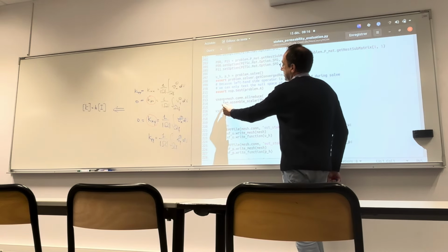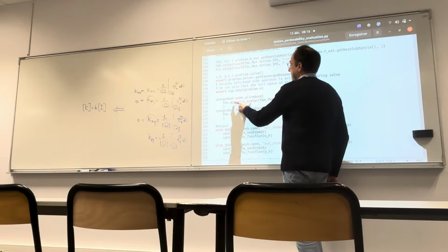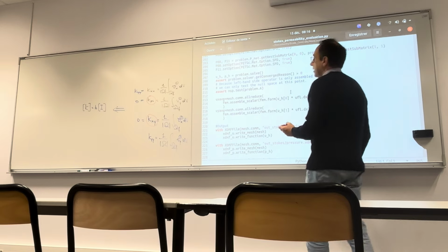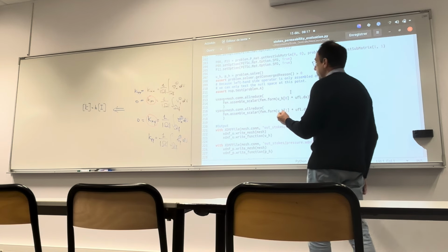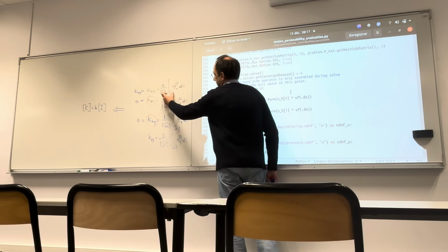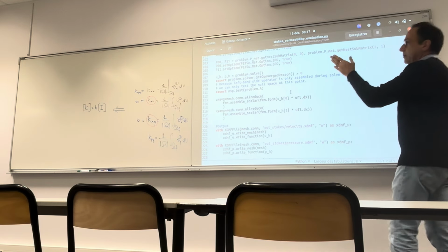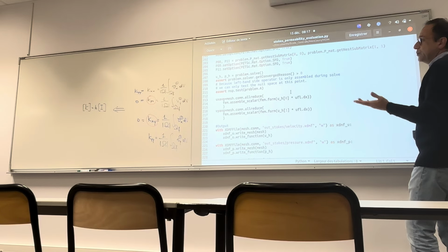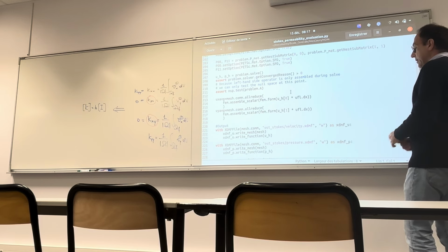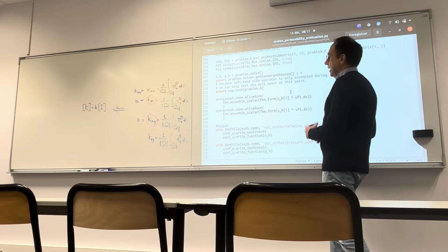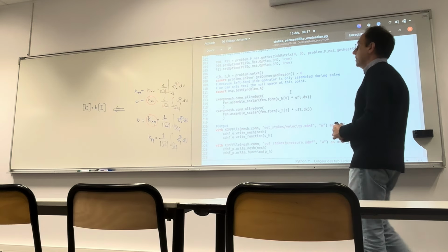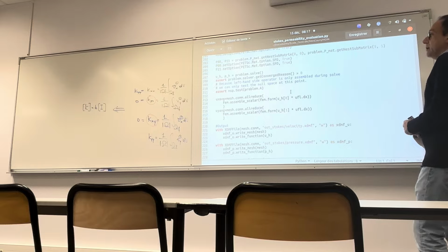When you see this FEM assembly scalar, or assembly vector, in this case scalar, because we are working with the components of the solution, component by component, this corresponds to doing the integral, essentially. And the 1 over omega is 1, so it's a unit cell, a 1 by 1 square, so it's just 1. So these two lines give you the average velocity.